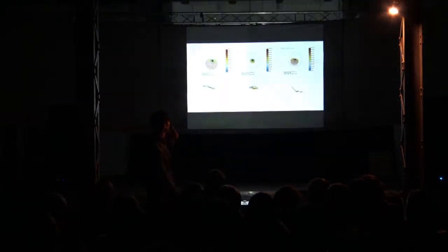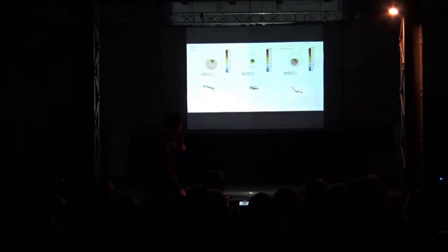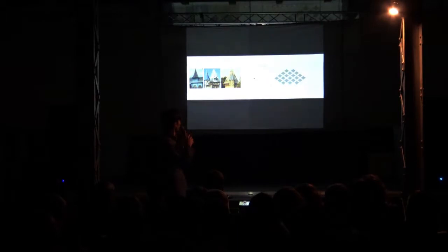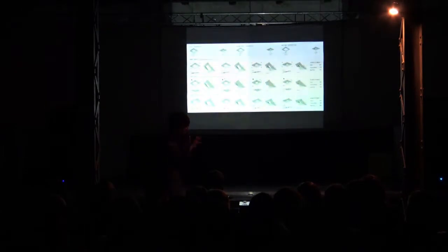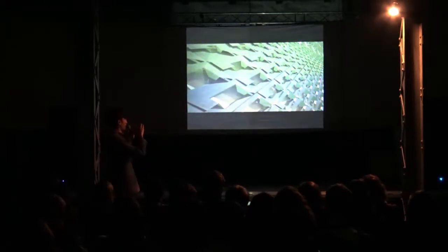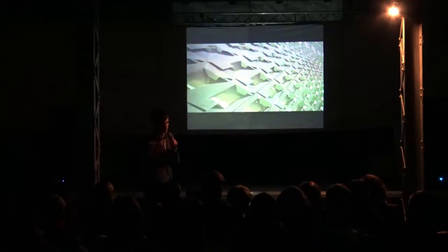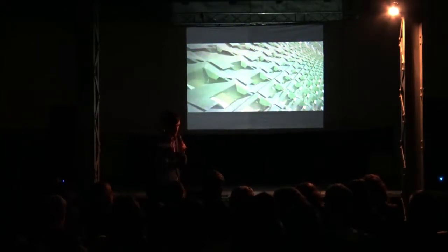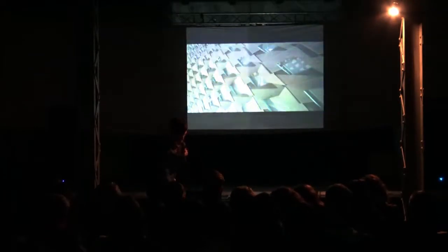All right, so those are the renders. And the reason why I'm showing this, again, is that the facade was run through Ecotect, and we were calculating the presence of the sun, again in correspondence to the context, so to the roofs of existing structures. We created a facade that was differentiating, but all the panels were flat, so it would be cheap to produce, but they were still differentiating in X, Y, Z axis to either allow more sun or complete shade from the sun.